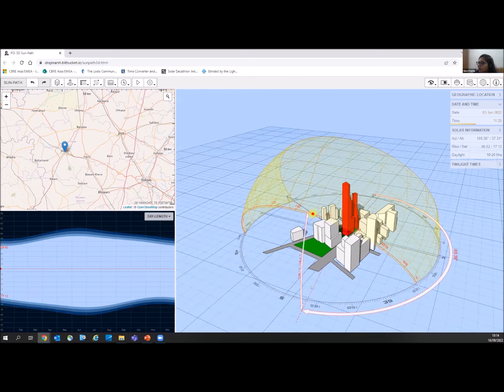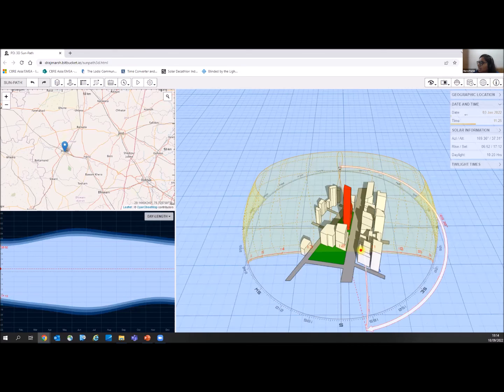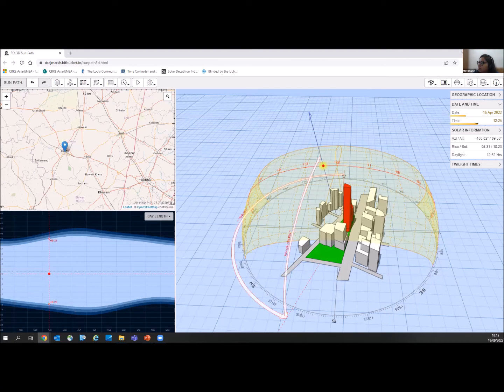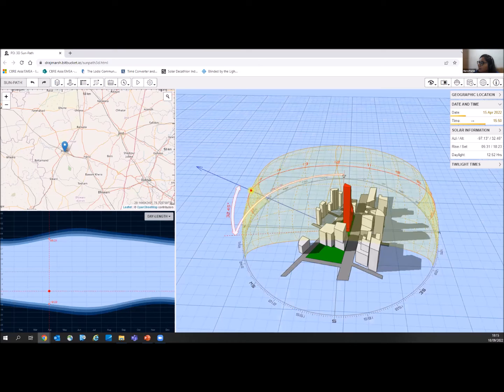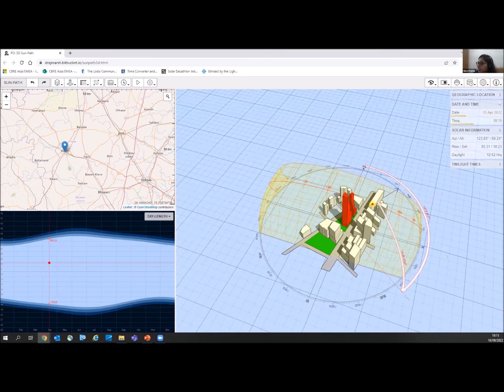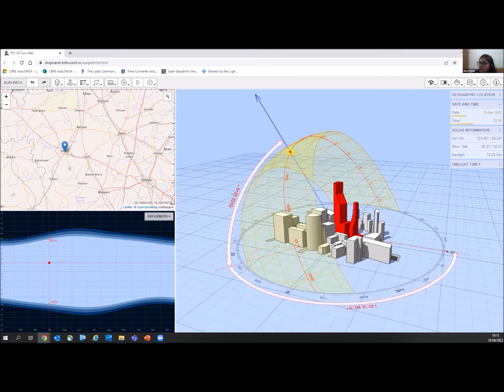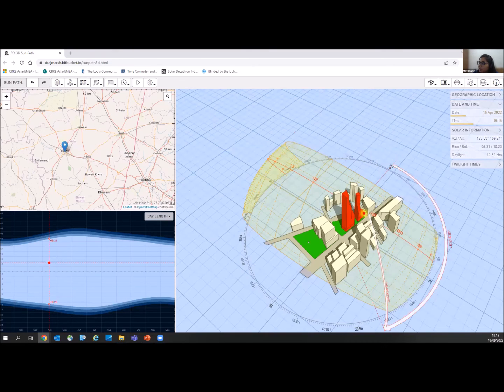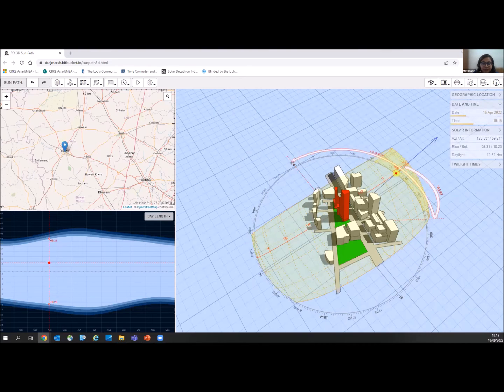So say if you want to shade for this location, you'll be able to check the time, and here will be the date of the year, so which month. Say you want to shade in April, and as per the irradiation graphs we already saw, we want to start shading from 10. So based on this tool, we'll see what the azimuth should be for the shading here. You'll have to shade at 59.26 if you want to shade from the 15th of April sun from say 10 a.m. onwards. So you'll be able to look into something like this in 3D and calculate the angles from this.